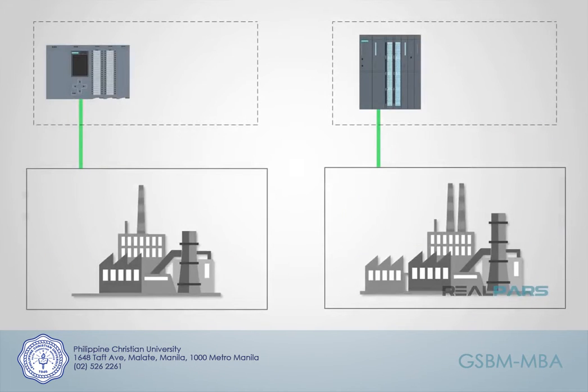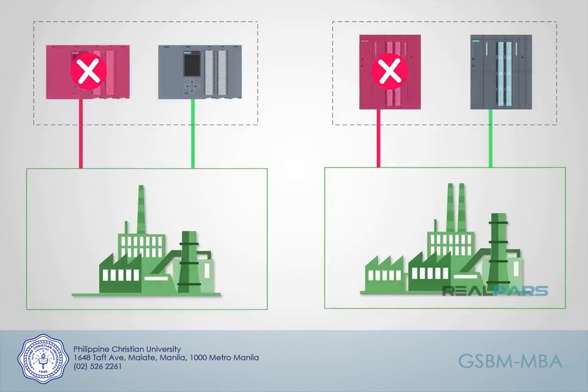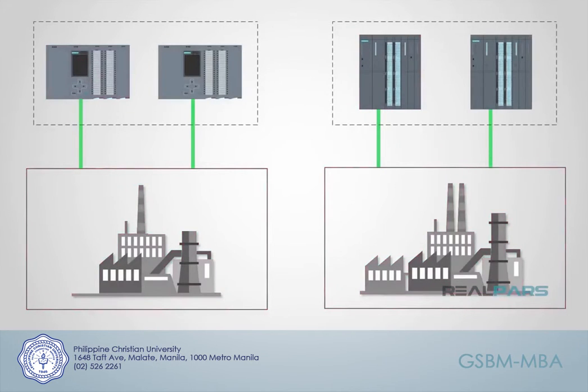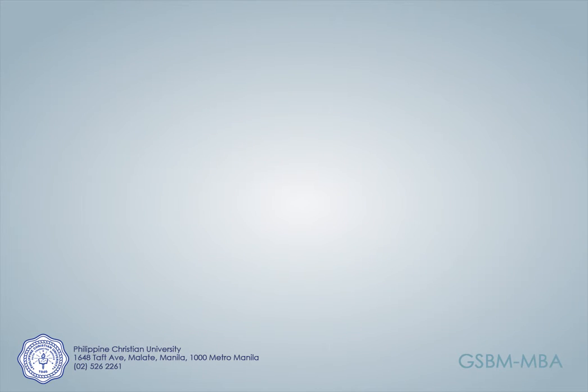There are indeed scenarios in which a PLC system would be the best option, such as smaller-sized processes, where you could employ redundant components to negate the possibility of process shutdowns. Without redundancy, you risk production halts due to the nature of a single processor controlling an entire plant. Redundancy may be deployed in either the PLC or DCS application.